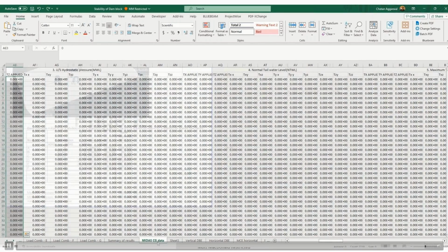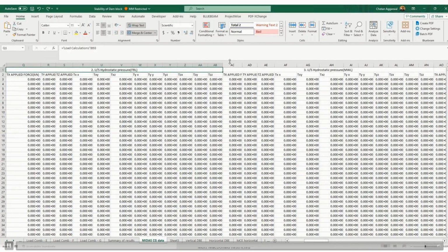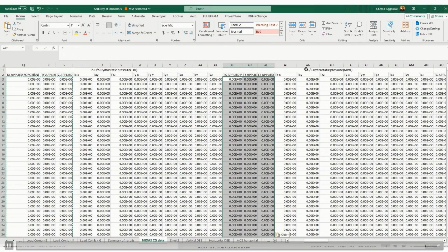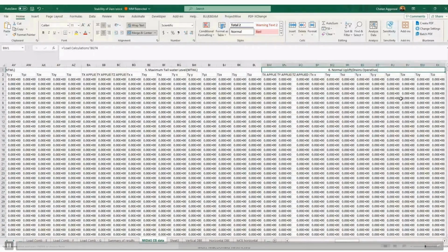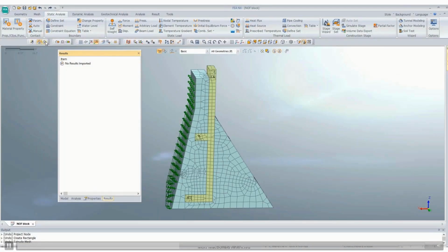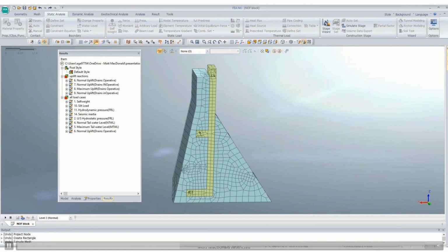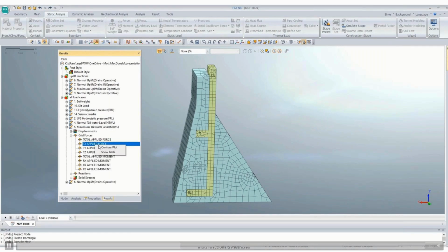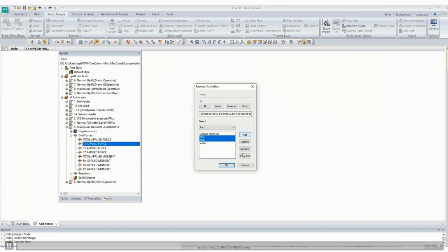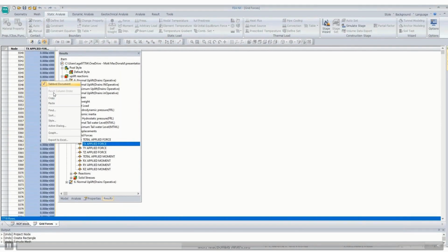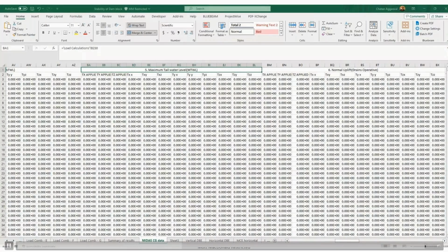Okay, so MWL, it is same as FRL, so I'll have this TX and TZ, copy it, and paste it here. Then we have normal tailwater level already compiled. Maximum tailwater level I will compile now. So I have these analysis cases with me. Go to post processing mode, and then maximum tailwater level, this one. Okay, so we have grid forces in X as well as in Z direction. So none. I'll need this one. Okay, copy it and paste it here first.